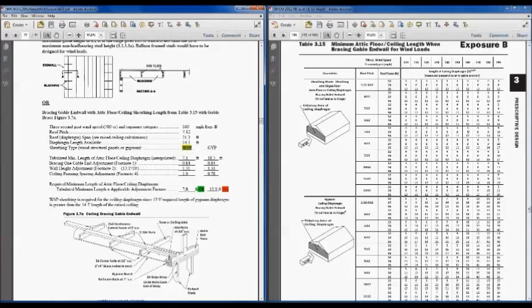It's the roof span. So I'm interpolating between 24 and 36 feet when the roof span in this case is actually 21 feet because of that raised ceiling. So that kind of throws the calculations off a little bit. So the roof span is 21 feet, and so that's why those numbers are smaller in this particular case. This is the roof span that you have to look at. So these are the numbers you end up with.